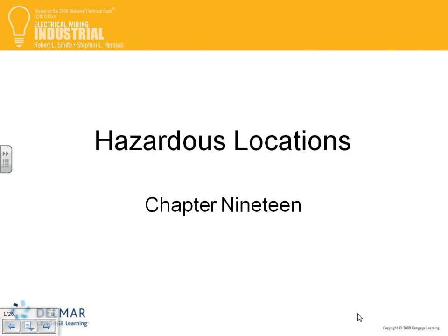Class 2, the dust, guys. Look at the grain and grain products, they are class 2. We have dried egg and milk powders, class 2. So on the second page, if these exist, they are examples of a class 2 location. Okay? Class 3 location, look at class 3. There are portions of rayon, cotton, or other textile mills. That's the ignitable fibers. There are flax processing plants, clothing manufacturing plants. Most of it is flyings related to cotton and clothes in a class 3 location.